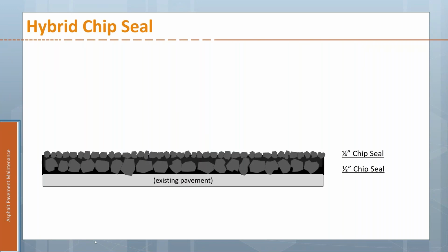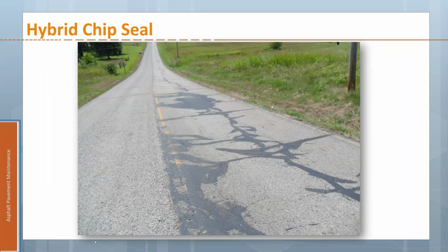On top of that, we came in with another layer, did a 1/4 inch chip seal, so a smaller surface type aggregate to make it a little bit smoother. And then on top of that, we came in with a fog seal and put it over the top. So that effectively painted it black, but also helped with chip retention for that top layer. So this was the project. The right lane, you can see they've done a lot of crack sealing, trying to get ready for this.